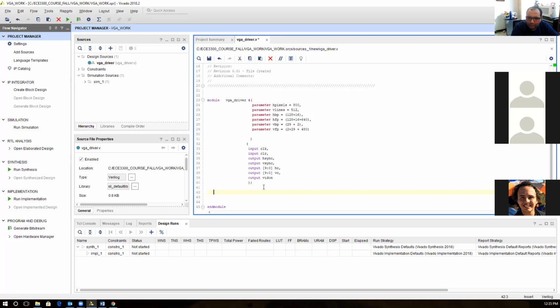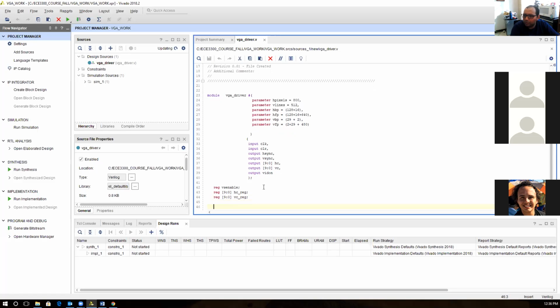So what I'm gonna do, I'm gonna make something that's called reg, and I will call it VC enable, and they're gonna be just one bit, single. Then you know I'm gonna also go ahead and say reg 9 to 0, and they're gonna be the HC reg, and another reg, and it's gonna be 9 to 0, and they're gonna be VC reg. You guys know what I'm doing, right? I would like to make it like a unique entity. Then I will tie this VC, HC reg, and VC reg to the HC and VC I have written here.